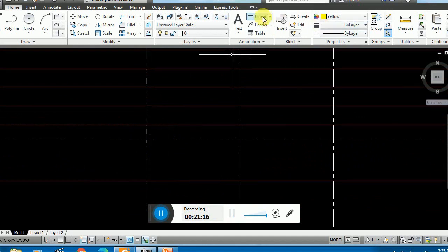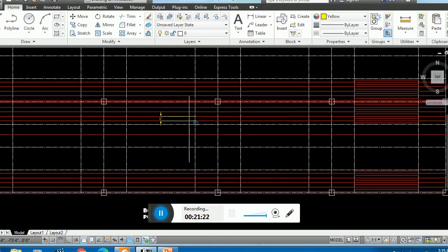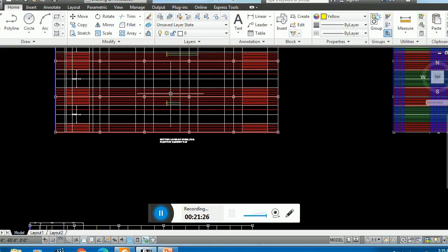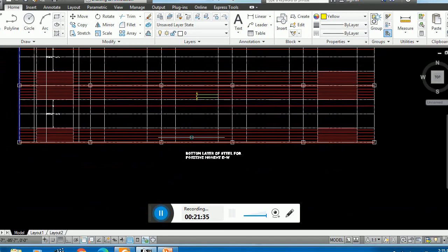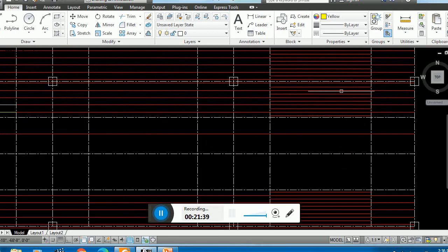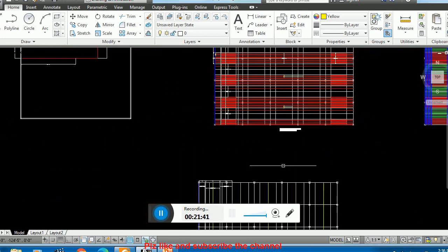Let me rub it, and again this to this 1 feet. So all the reinforcement is number 5 at the rate of 12 inch center to center. Okay, so this must be clear. And this will be in east-west direction. Similarly, in this middle strip, this is column strip, and similarly exterior. But in the first exterior panel, you have to change a little bit because there is greater movement.